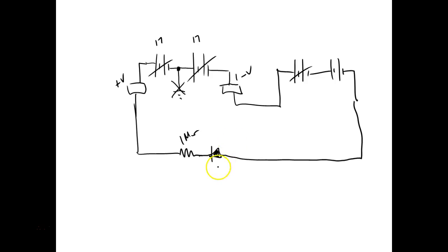And then, of course, what we'll do is we'll measure the voltage drop across here. We'll use 2 meters. And then we'll have another meter hooked across there. That way we won't have to move them while we're doing that. And then I'll start adjusting this. These guys put out around 2 volts. We use 4 power supplies. They'll start off with 8 volts, which is still well below that. And I'll just start turning them up. And then when I get up on the 3rd one, the 4th one, I'm going to go real slow because that's where it's going to do it. We should see it break over up there.